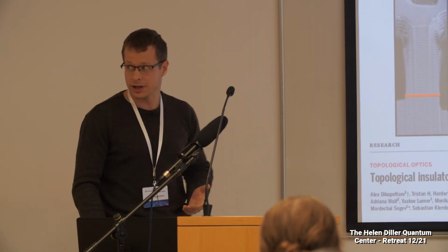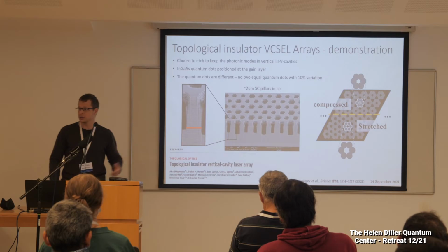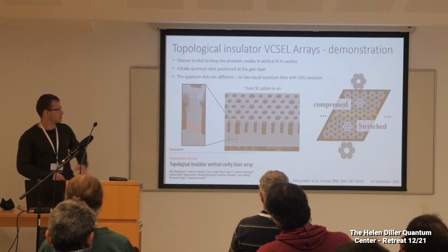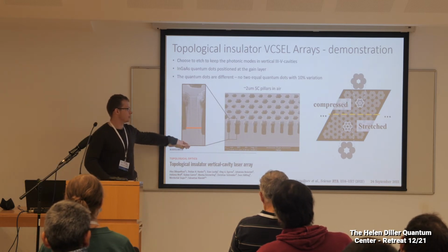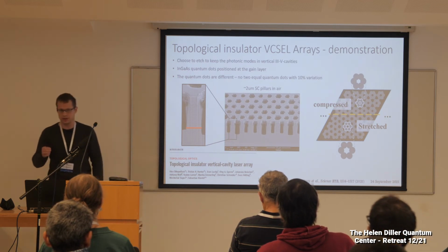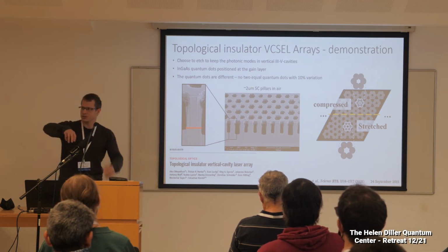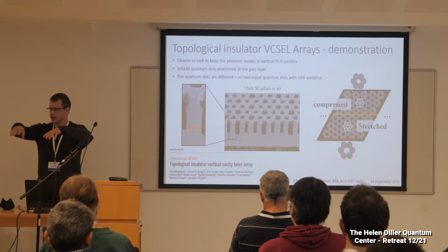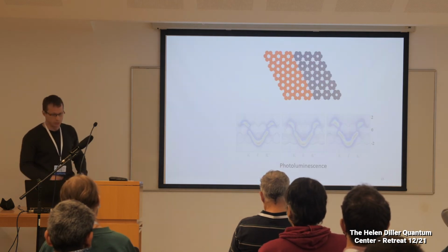Now, we went and fabricated this device. This was a collaboration with the Würzburg University. And this, you can see a wafer. The top and the bottom are Bragg mirrors. And in the center, the red line is the cavity with the gain medium. And we etched the geometry of the crystalline. And we measured what we got.